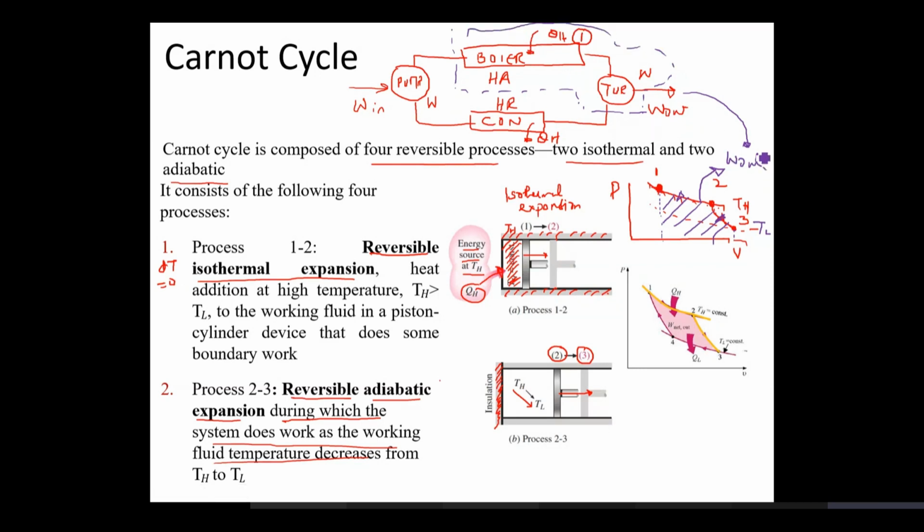In the first half of the cycle, there is work generated and heat involved. So from 1 to 2, heat QH was added to the system. So heat addition and work generation. So 1, 2, 3. During this path, half of the cycle has completed. There has been heat addition to the system isothermally, and there has been adiabatic expansion. So there is work out which is generated as a result of this expansion. Half of the cycle, is it clear to you?